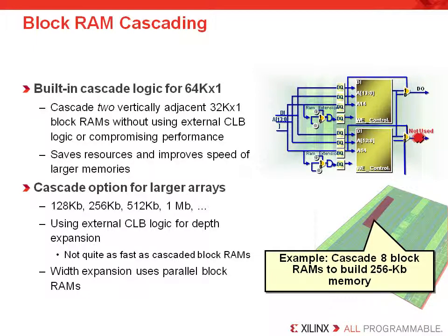Now the 7 series block memories allow for 2 block RAMs to be cascaded together with the dedicated routing resources that runs between them. Now this is important because it enables you to preserve the timing, but is only allowed between only 2 neighboring block RAMs. So you cannot cascade more than 2 blocks either way.